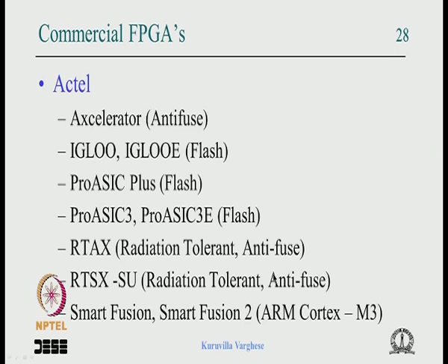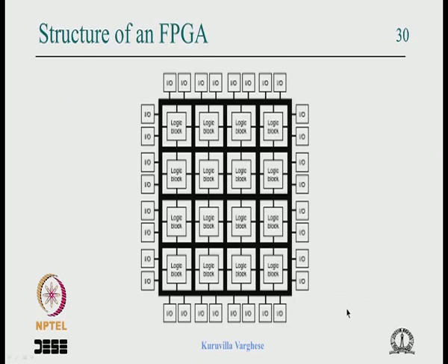Once you program it, it cannot be erased and reused. So it's not very good for prototyping. You can simulate, but then you want to test the system during development. It's not a good idea to use anti-fuse technologies. Maybe it has to be tried in a static RAM kind of FPGA, and once it is matured it can be transferred to the anti-fuse kind of technology.